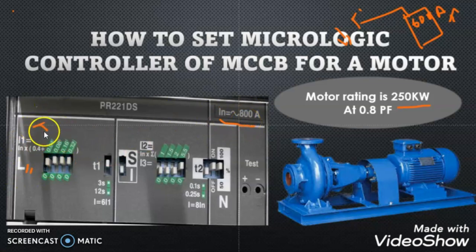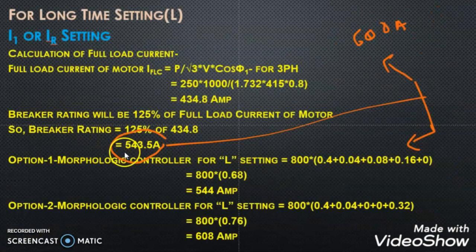The rated current rating of the breaker can be changed by using the dial or this dip switch, which comes under the L setting. Now we will see how we will change this 800 ampere breaker to a breaker which has a current rating of 543 or above. So let's see.